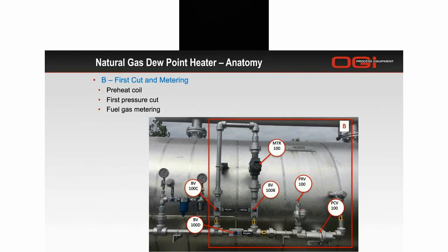So after the relief valve, we're going into our meter run. This is the meter block and bypass loop. As we're flowing from right to left, the gas has two paths to go. It can either go in this vertical direction through the meter, MTR100, and then down the other loop, or go straight across, where it really just bypasses that.